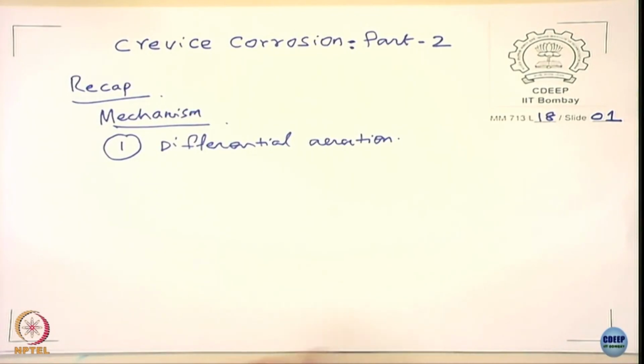So the crevice starts corroding over a time period, because it is diffusion controlled. In a crevice there is no convection, as the dimension is so small, so the oxygen within the crevice steeply decreases with time, and so it becomes an anode. That is the starting point.